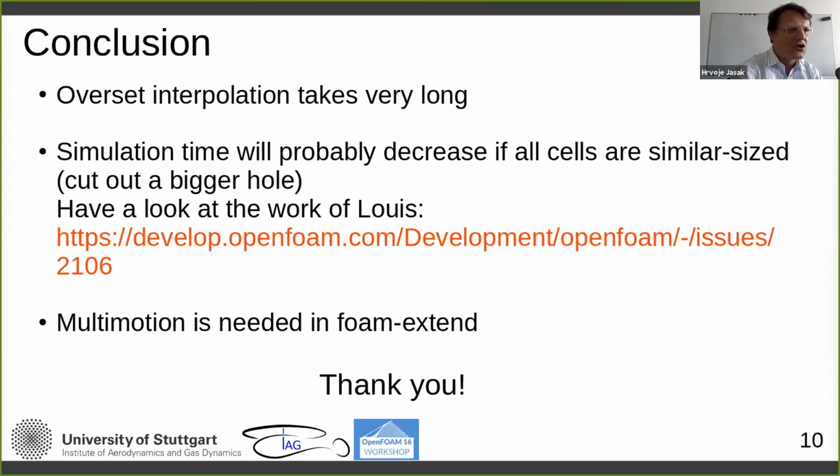The next question is from Jonathan Fellback, saying, when you talk about AMI, is it just regular solid body rotation with conventional dynamic mesh, or are you doing something else? AMI is just a regular solid body rotation. We have the rotation of the entire rotor, and we have the rotation of the inner blades separately in 2 pockets. So it has nothing to do with overset.